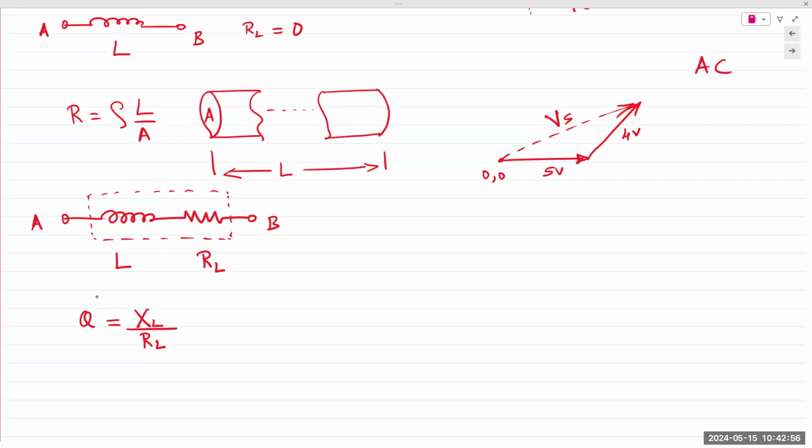So in this week's lab, lab 6, we simulate a bad inductor. The labs were written when we didn't have low quality inductors, only high quality inductors. So what we would ask students to do is add an external resistor in series with your high quality inductors to simulate or model a bad, low quality inductor.